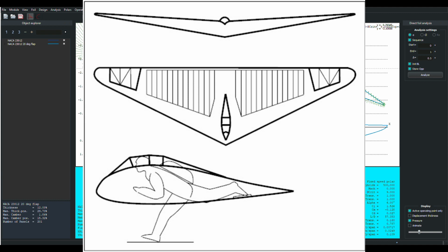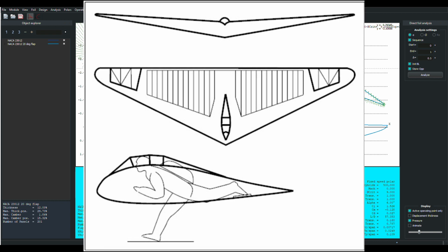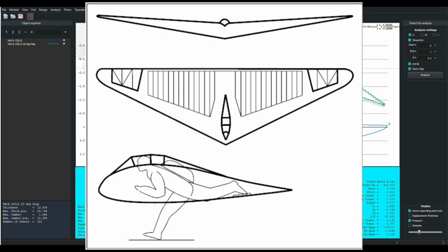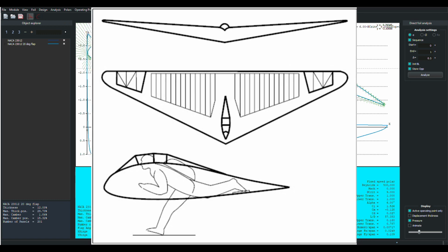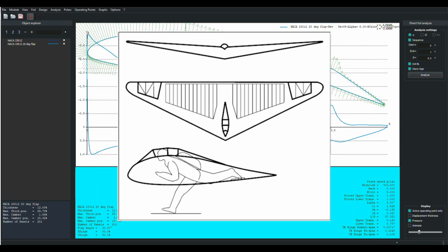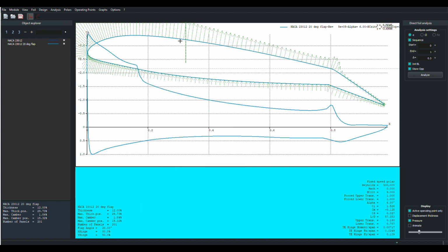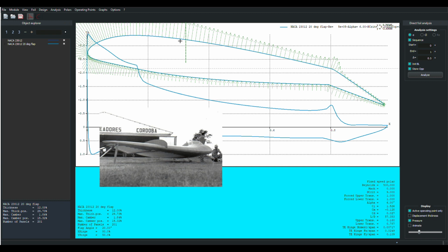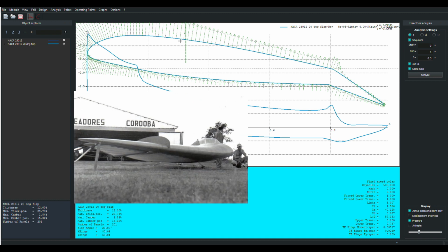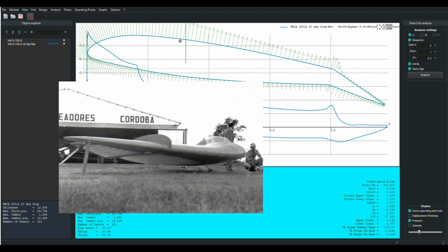So you can see that they were dealing with this problem also, because as a hang glider, it's inconvenient and heavy to create a second spar like I did for my elevons somewhere in the middle of the wing. It's just easier to say, I'm just going to hinge it to the spar and be done with it, which is what the Horton brothers did. And then I don't need as much span to get these short span elevons on here. And if we take a look at another view of their glider, you see giant wing fences. They're really tall.